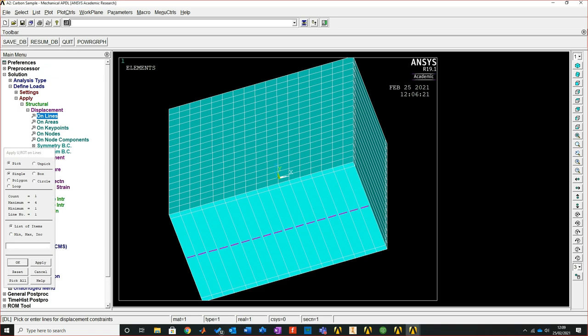However, let's say that was the wrong line. What I'm going to do is right click once. You see the arrow pushes down. That response of it going down is in cancel mode. So if I click it now, it turns it off. So I've got to right click again to get the arrow pushing back up, and now I can click here and click over here.